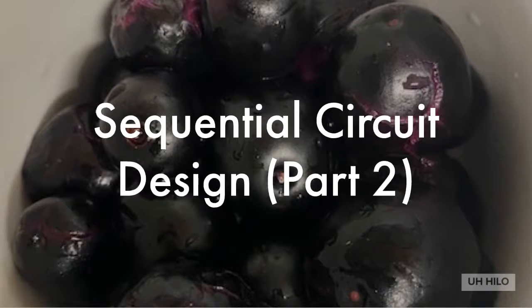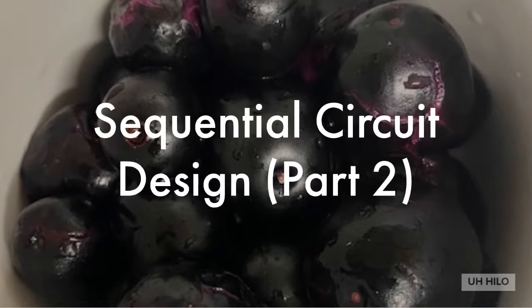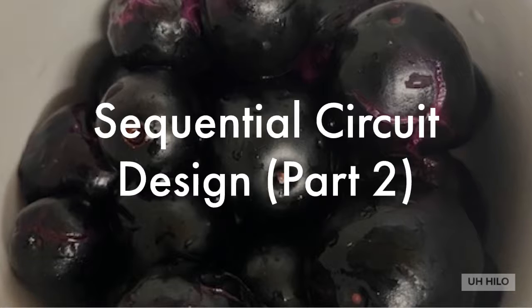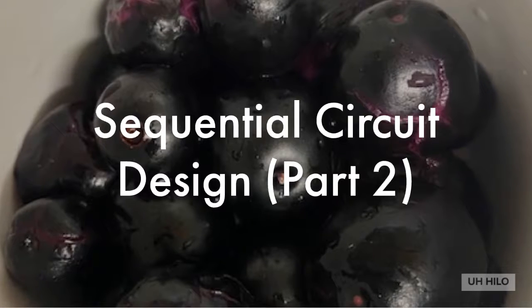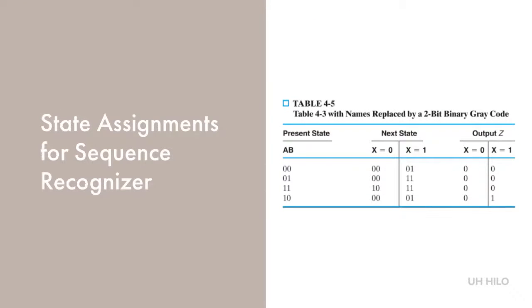In the last presentation, we looked at the process for sequential circuit design and even created a simple sequence recognizer. In this companion presentation, we'll look at how to expand on this design to make it better. We can use the sequentially assigned gray code or a one-hot code for the sequence recognizer design.